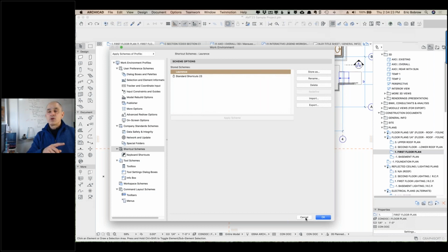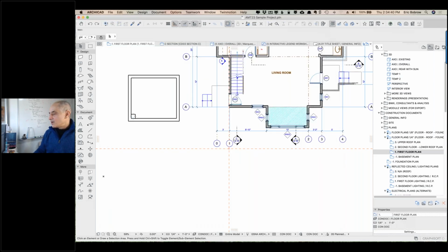So one place where you could lose it, you might have a custom environment and have more than one ARCHICAD open, and maybe you've customized it in one and not the other. And then you quit out of one, it's still active, but when you quit out of the other, it gets overridden. So that's going to protect you there. All right.